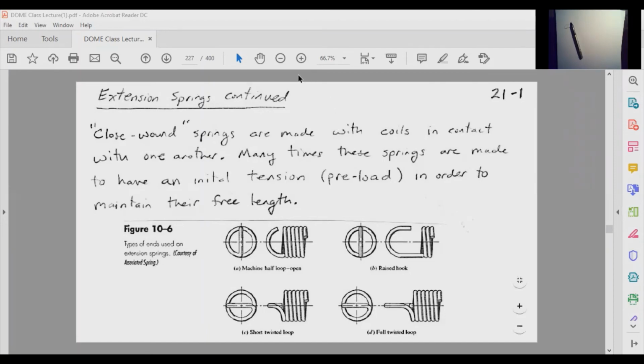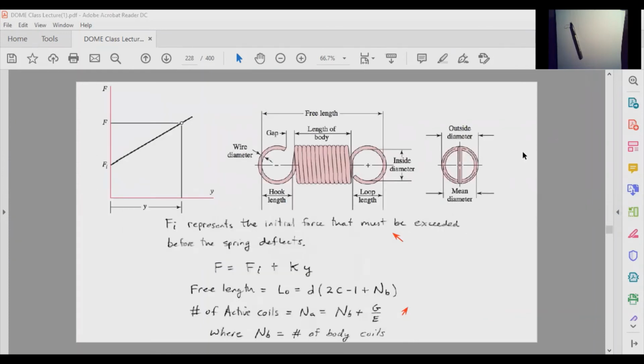So let me just draw that quickly. So this would always be your R1, and then R2 is going to be this one. We need those two to be able to calculate the stresses in the hook. Just like in the case of any mechanical component, you have to calculate the stresses at the areas that you think are going to have the highest stresses, and the highest one is going to dictate your maximum force, or is going to give you the lowest safety factor. The weakest element is going to be your control element.